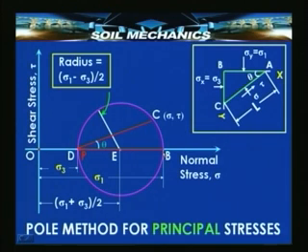That means the plane BC will have to be a line which is horizontal passing through the point B. So, from point B, if you plot a line which is parallel to the plane AB on which this stress sigma 1 acts, then the point P becomes the pole, and PC at an angle theta will give you sigma, tau, and PC is plotted parallel to CA. Or alternately, plot 2 theta with respect to the line DB and get the point C.